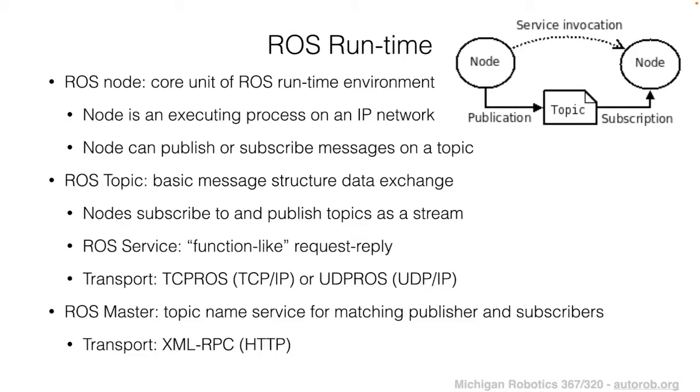We're going to look at some examples coming up, but just to ground it a little bit, you could have topics, for example, for image data, right? You might be able to pass image data messages, or point cloud messages, or motor control command messages. Each of these different messages would then be organized by topic so that each node is able to subscribe or publish to the correct location on the network.